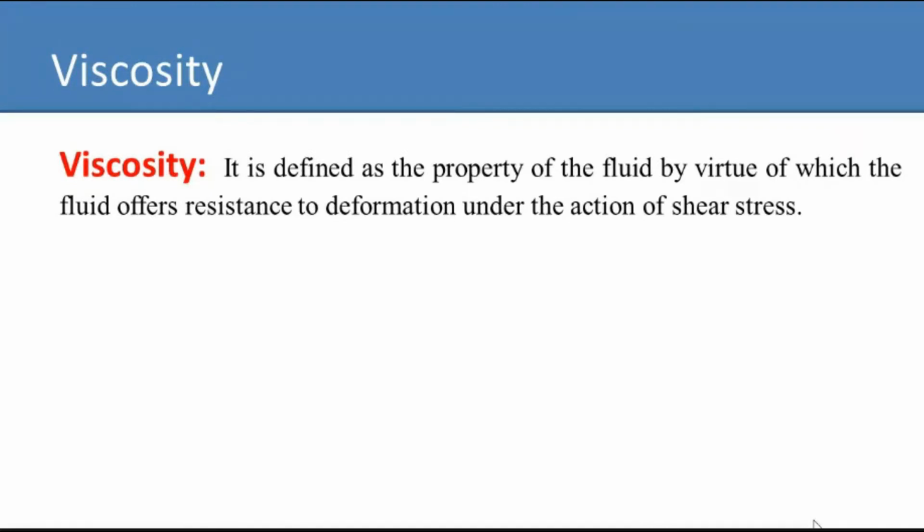We had already seen in our first lecture that if we consider an imaginary cube of solid and apply the shear force Fs, this solid will have some deformation like this, a shear deformation. And what will happen if you remove this force? This solid will regain its original shape and size. So this property is nothing but the elastic property which is shown by solids.